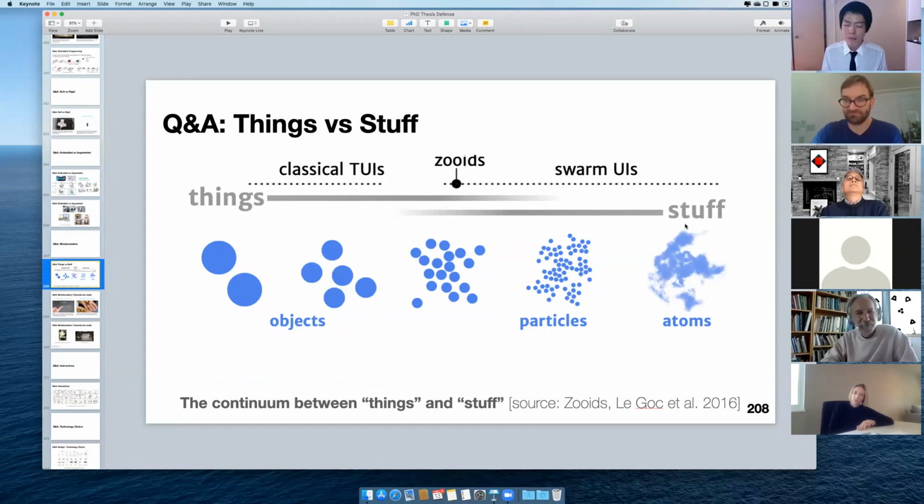For the active elements, I think the technical limitations are, one, actuation, which is mainly the motor, and another one is the battery. Because these two are the main components which require a large space. For the motor, I did a kind of review, which is kind of a Moore's law, not a drastic Moore's law, but the size of each motor is continuously shrinking. So it could be possible to make millimeter scale swarm robots maybe within a decade.